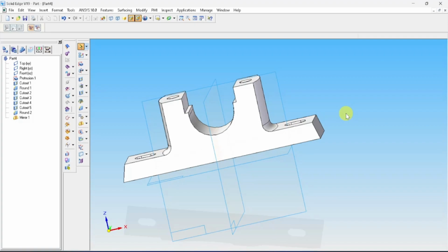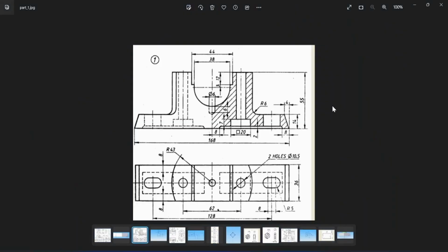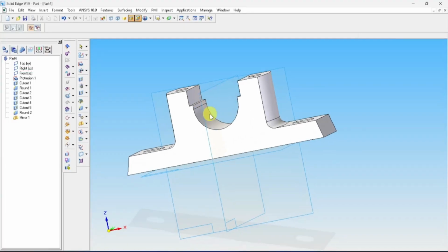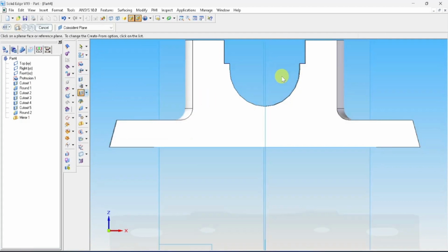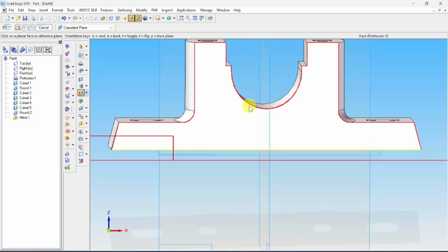So next step is we need to create this oil hole. So this oil hole will be created from this edge for a depth of 6 mm and diameter is 6, and also at the end it is conical shape. So here the thing is, when you are generating the hole, that is this hole command, it will add the coincident plane. Now in the SolidEdge software, any curvature surface is there, that will not generate any kind of hole as well as protrusion also, because it will give an error as zero thickness.